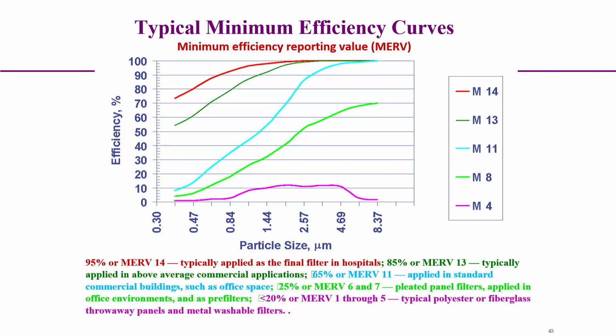Here, if the MERV rating is 14, this means very high filtration, very small particle pore size. Okay. So, here the particle size is given, and these are the respirable particles as we have seen.